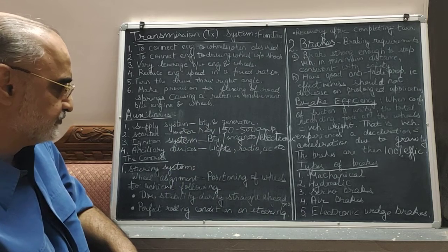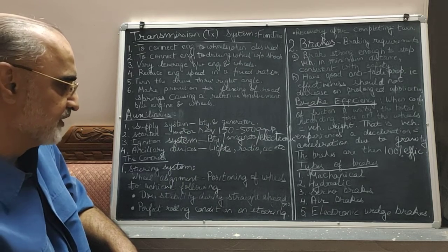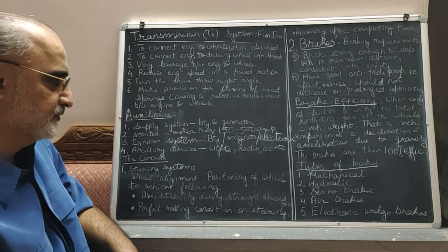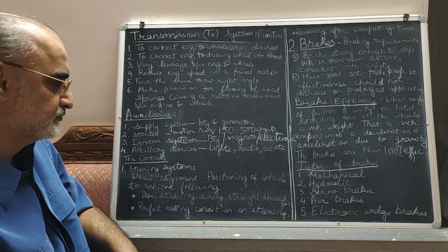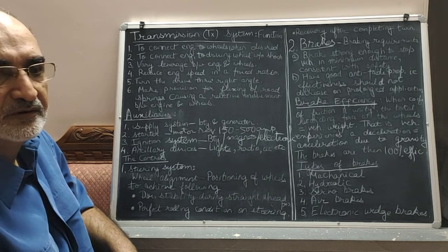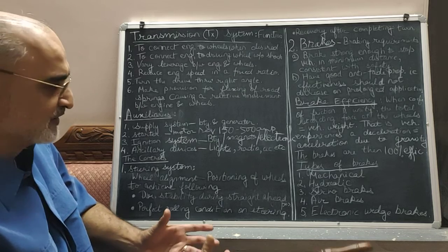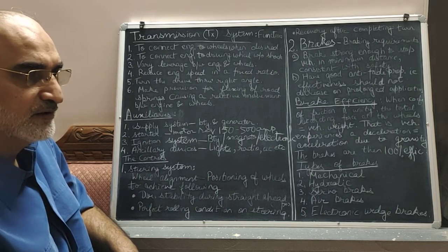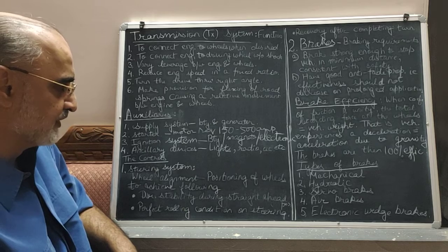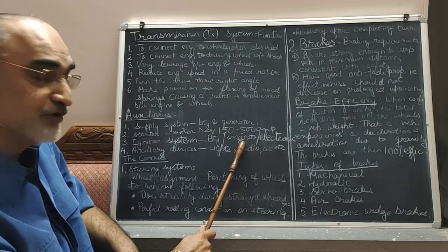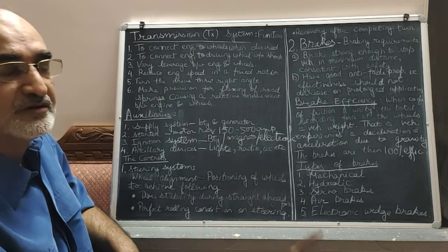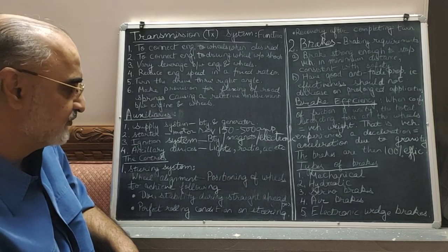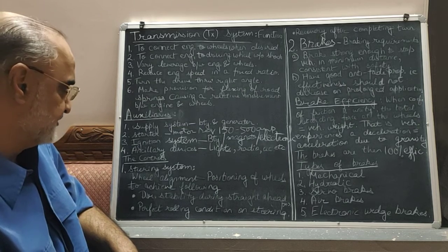The ignition system, there are three types of ignition systems currently. One is from the battery, magneto, and electronic. In magneto, it's nothing but a small generator with primary and secondary windings, and there is an iron magnetic rotor, which gets the drive from the engine, rotates and produces current, which through the windings is fed to various parts of the engine.